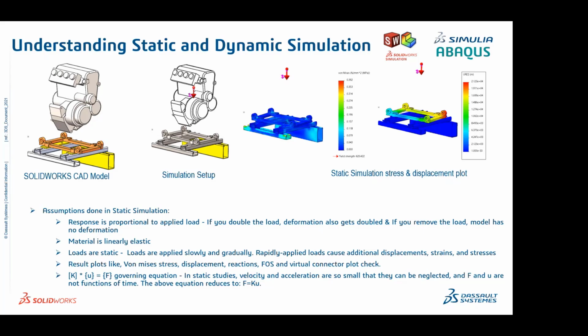It might be with respect to large displacement or sliding or contact, or with respect to the material as well. So this is one assumption we consider. And yes, the material is linear elastic. And this is the key assumption we make with linear static analysis, that loads are static. So loads are applied slowly and gradually.